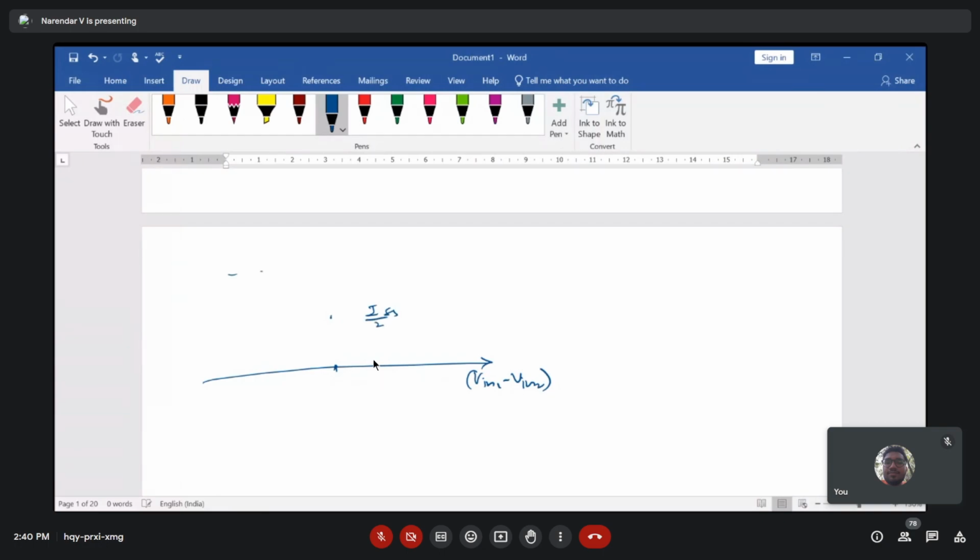And what we can notice here is that the maximum current that you can get is ISS, and this axis will indicate the current I, and this is 0 point, and we are talking about this range VOD, right? This is your VOV overdrive voltage, and this is your minus VOV overdrive voltage, and this is called the range of your differential amplifier.